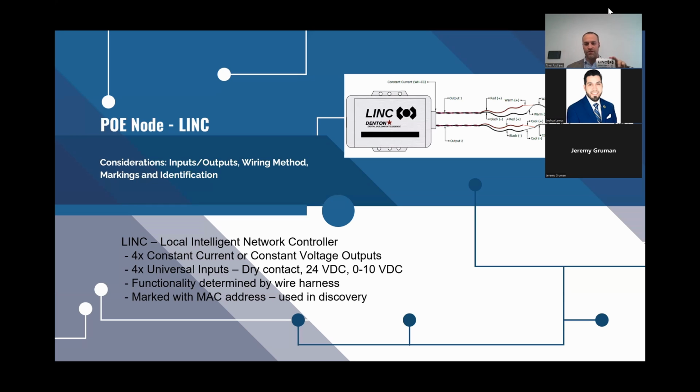Jeremy, great question. The PoE port powers one node every time. You power one node, and depending on the manufacturer, that one node may be just one light fixture. For PoE Texas, it is 4 outputs.